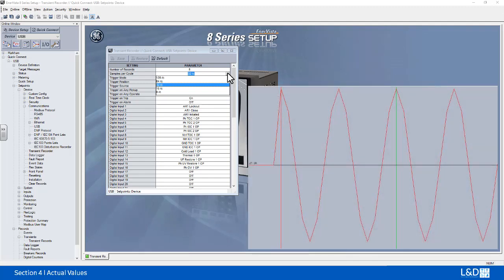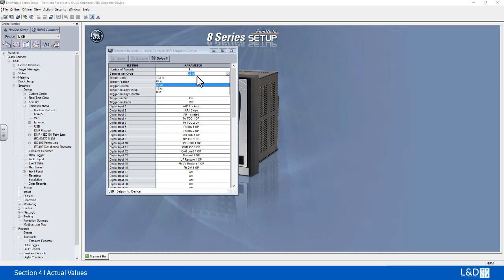If we want to record much longer events, we can reduce the sample rate just to see the longer events. And also we can reduce the number of records. With a smaller number, we can record much longer events. Trigger mode can be override or protected mode. Override, the new events cover the previous one. Protected, it just stops recording at a certain length.